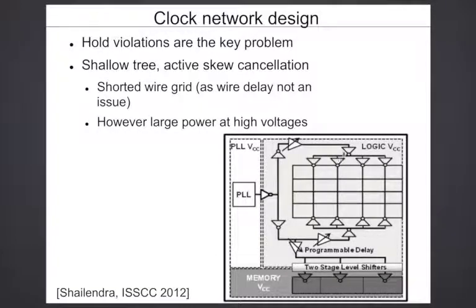Correct. The arrival time difference could happen due to different propagation delays and different delays of these individual buffers. Right? That's what leads to clock skew. The thing is, the clock skew hopefully is still a small number. It's still maybe at most 1 gate delay across these. So it won't be too large. They won't be off by multiples of gates.